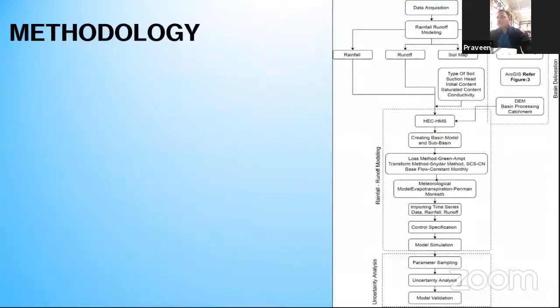Then in that, again, there are so many steps: you have to create the basin, give the loss methods, define the meteorological model, import the data series and the control specs, and then do the model simulation. All these steps will be covered in the further slides. After you have done the modeling, it will simulate. Okay, you will simulate the model.